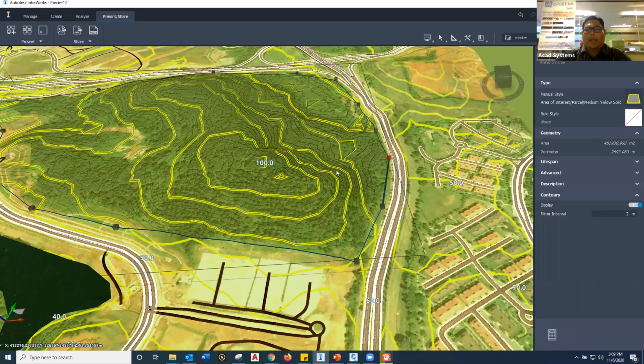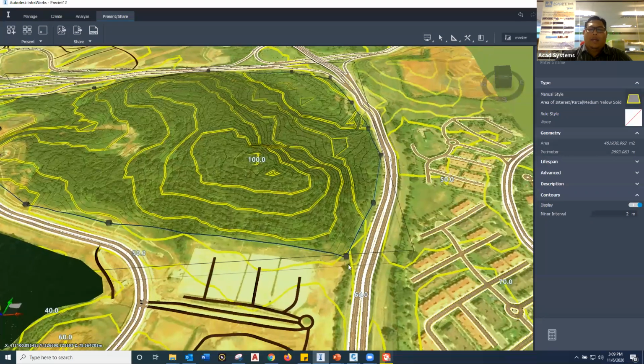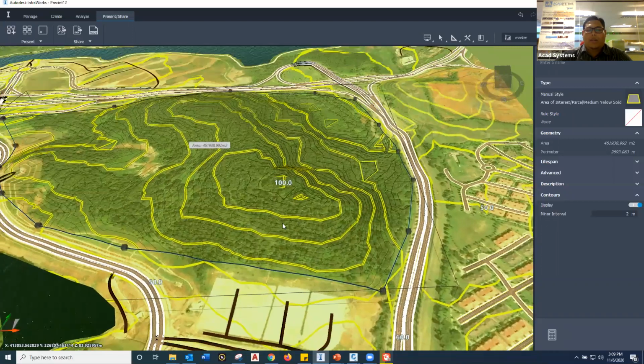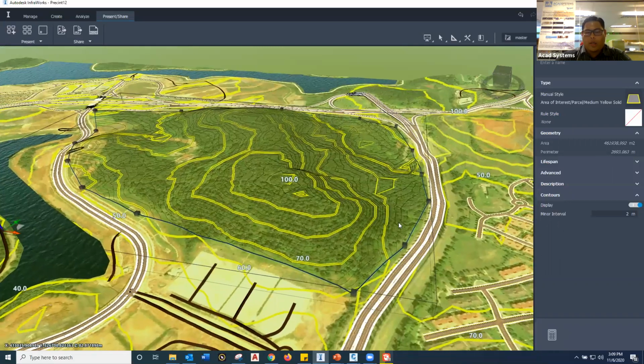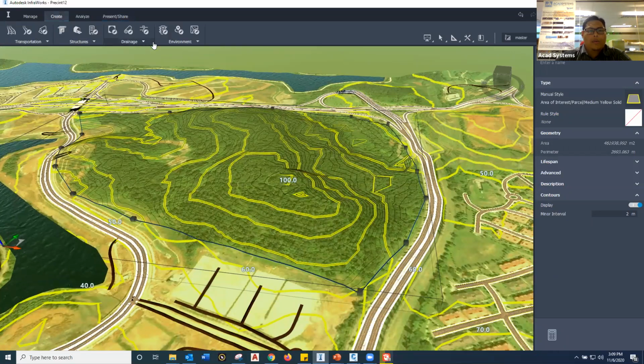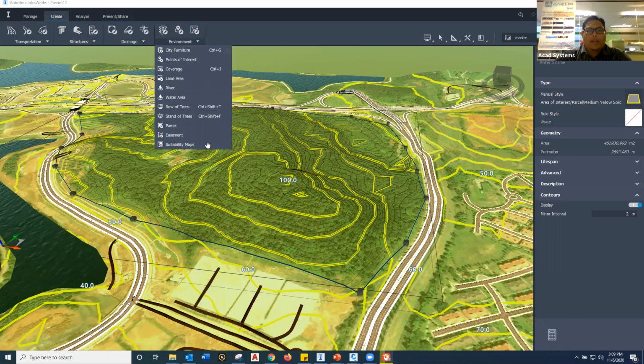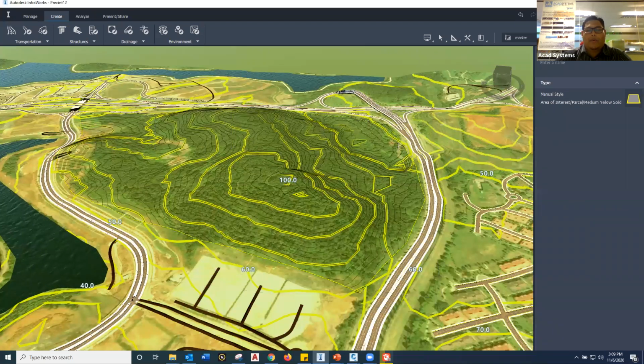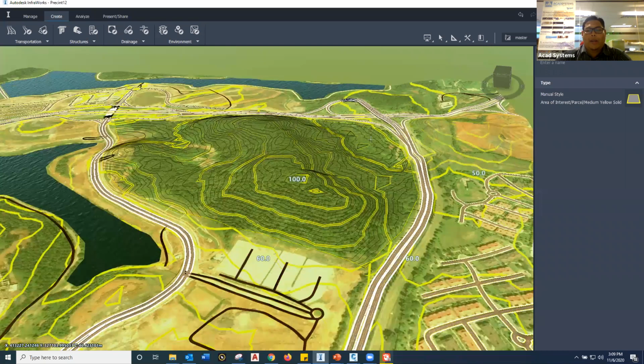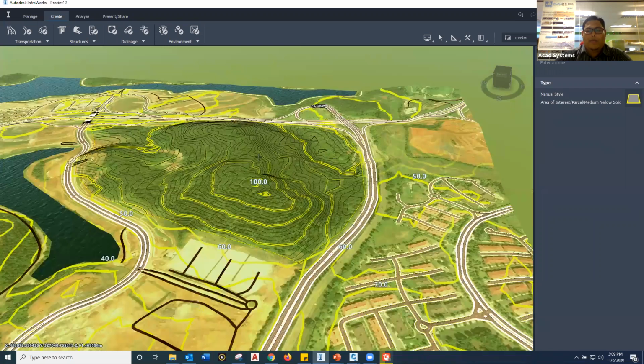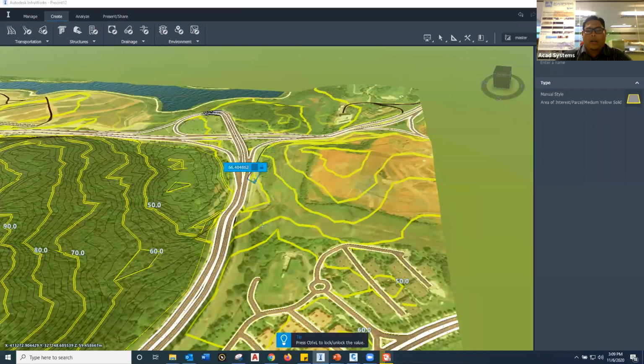And before we go further, you can also specify all the nodes that you see from the blue lines and the black dots, the black box here. Sorry, not the corridor. We call it the parcel. Okay, so this is what we'll see. Let's say you want to create a parcel for the site. I'm looking at the other areas. So let's say that we're going to create a parcel for this area. What you need to do is just create the area for the parcel based on the line here. Create the line, and once you're done, double click to the endpoint.